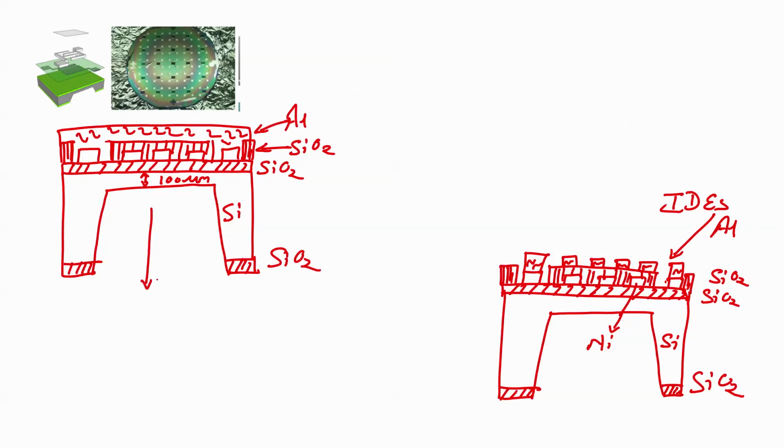So, the next step is spin coating photoresist, right. Quickly we will spin coat the positive photoresist. After positive photoresist, we have to perform soft bake. After soft bake, we will use a bright field mask and load it onto this wafer, like this.